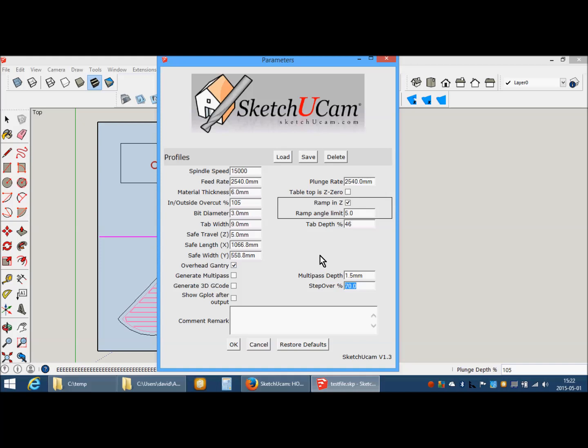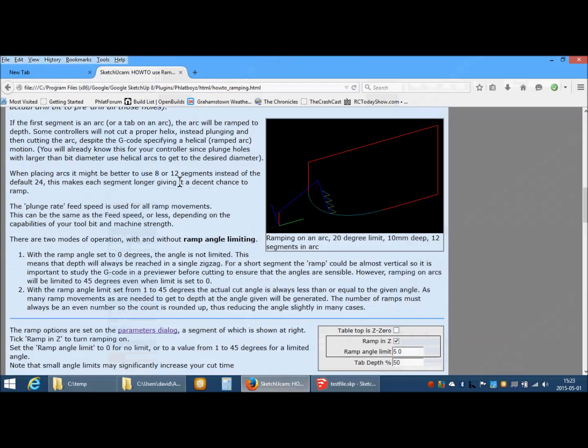This means that, for instance, cutting an odd-sized hole that is a multiple of the bit diameter plus a fraction, the last pass will be that fraction of a bit diameter deep. This may be a good thing, and it may be a bad thing for surface finish.